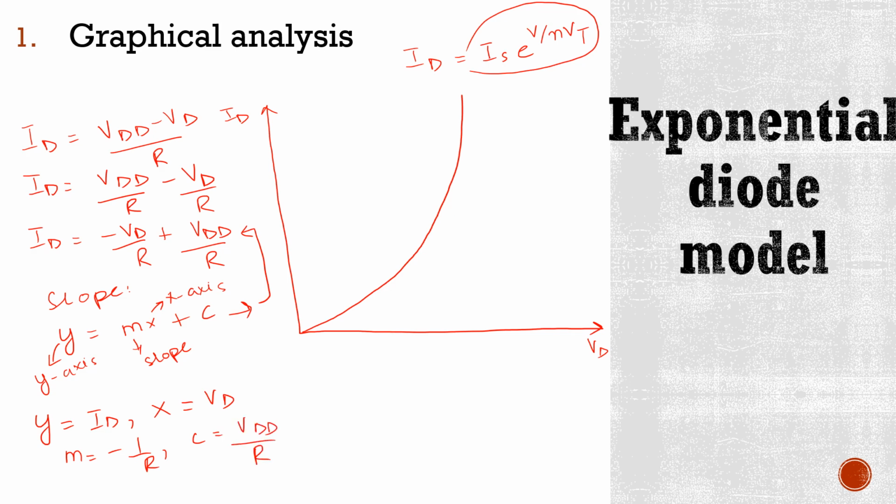So how are you going to draw the relationship that we obtained in this second equation of diode current on this IV plane? We draw this relation something like this. It means it is a straight line which is representing the diode current equation obtained from KVL.